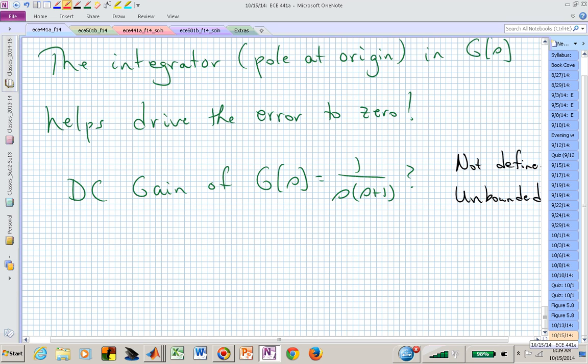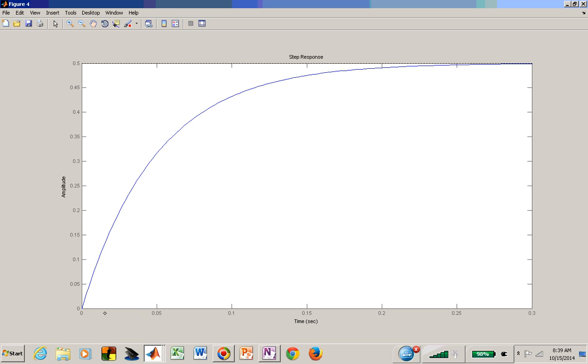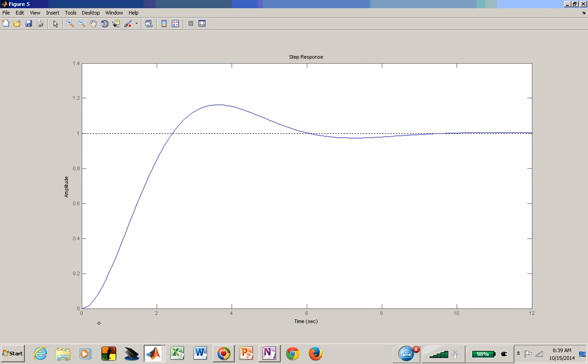What have we done so far with these responses? That was a pretty vague question. But we commanded these with what kind of a reference signal? A step. All 3 of those were excited by a constant input, and that constant in this case was a unit step. And we were able to infer or learn something about the steady state error.